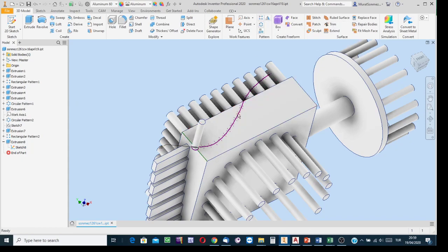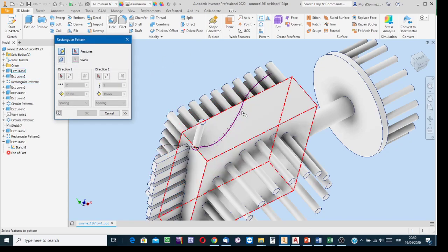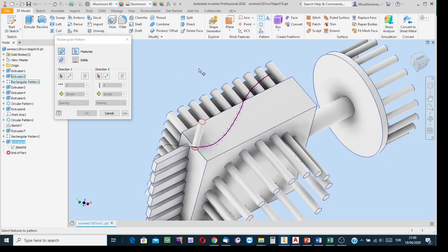Path array. Well, in this example, yes, the valuable part of this classwork is how Excel data is imported to Inventor and how the curve is fit. I think I managed to answer that question. And then, yes, the rest is array copy. In this example, I had this curve just to be able to create the path array. Okay, rectangular pattern, although it is a rectangular pattern, well, indicate this feature. Click on the direction button, indicate this path. Okay, and then along the path, create the copies.